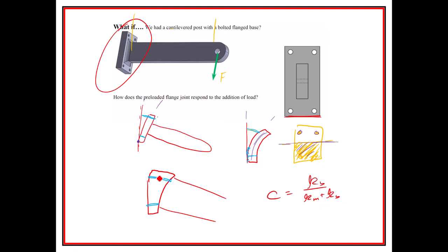So the external load that would be incorporated right here, due to this section, let's just call it P, for instance, the actual load of the bolt would be equal to C times P plus Fi, right? So it still has preload, but the member uncompressing now in this concept is the same thing as the flange from the previous class. So I thought that was an interesting additional piece of information on this kind of scenario of trying to distribute forces in a section.